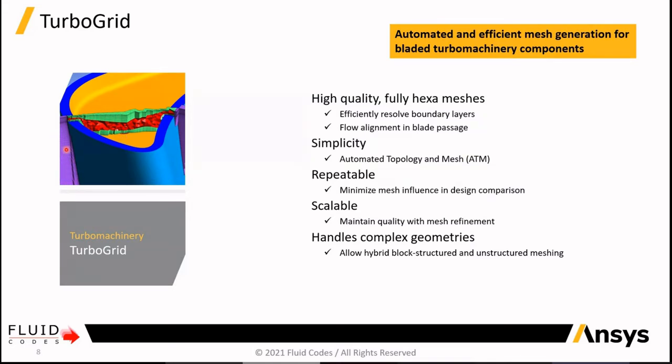So in the main passage, you have a full hexa mesh, very nice, very accurate, super refined, as you like. But when the topology is more complex than a single, simple blade passage, then you have this hybrid approach, where the tool is able to capture these details with an unstructured mesh, and the mesh will be conformal at this stage. So this is another tool available.